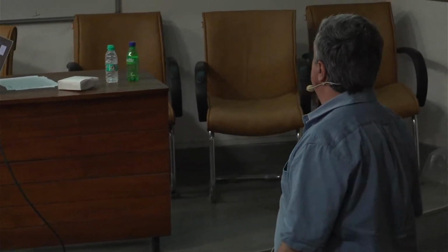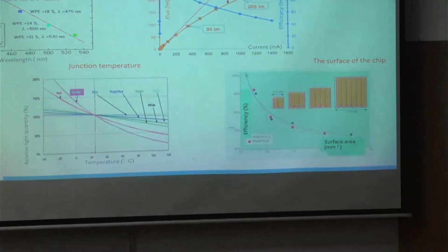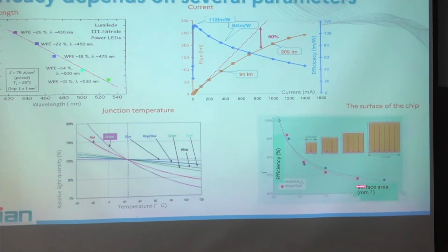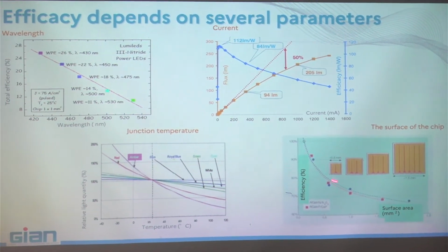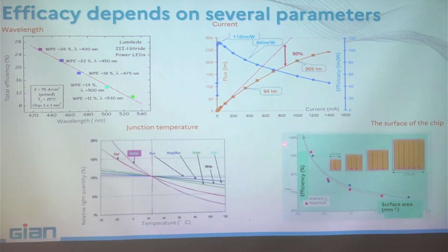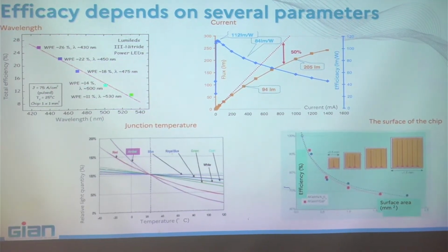They produce much more lumens, but then most probably the efficacy will be less, 80 to 70 lumens per watt, which is not interesting. Never boost LEDs beyond the value that is given by the producer. And the same thing, when you increase the emitting surface of the chip, you decrease the efficiency, and that was the problem between the 1 watt LED and the 5 watt single chip LED.